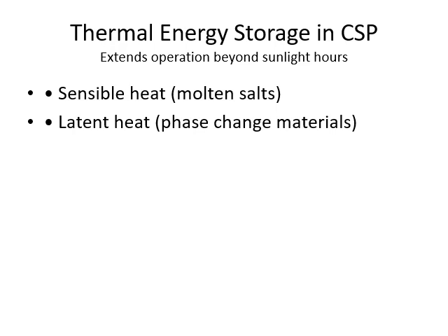So paraffin wax will be melting around 60 to 70 degrees Celsius just for a low temperature application, but when it's melting it is capturing the latent heat. Okay. And later on, after the sunset, this molten paraffin wax will be releasing back its latent heat again because it will be solidifying. So latent heat storage gives us this possibility of capturing the heat due to the high amount of latent heat.